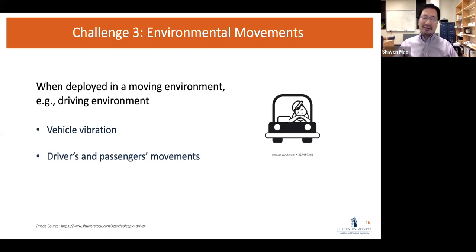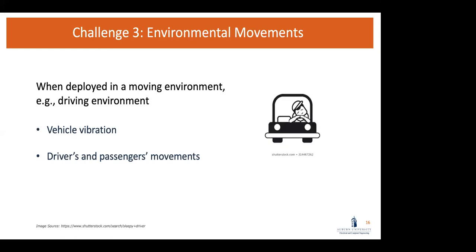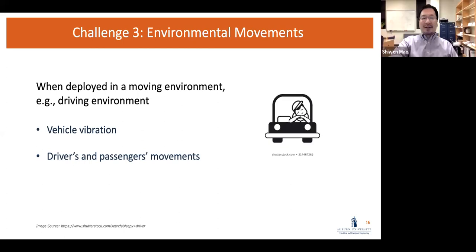How about using RFID tags to measure the respiration signal of the driver? That can be an indicator of the driver's condition. If the respiration signal gets very smooth and slows down, that means the driver is tired and close to sleeping.